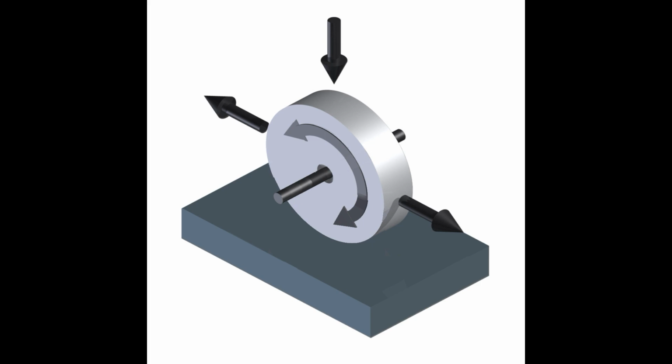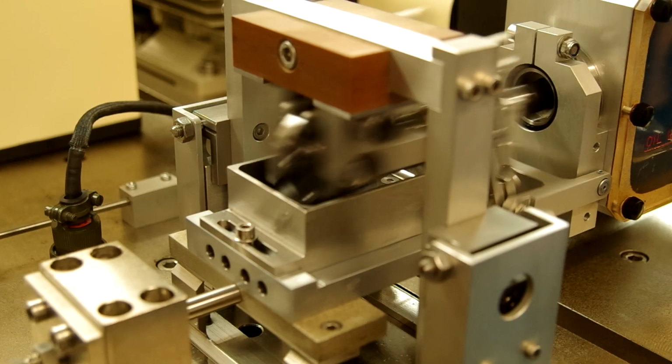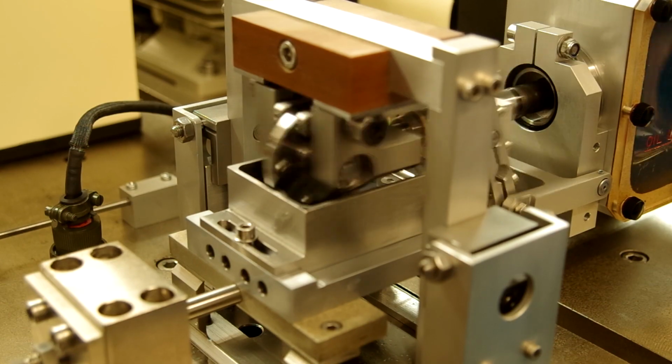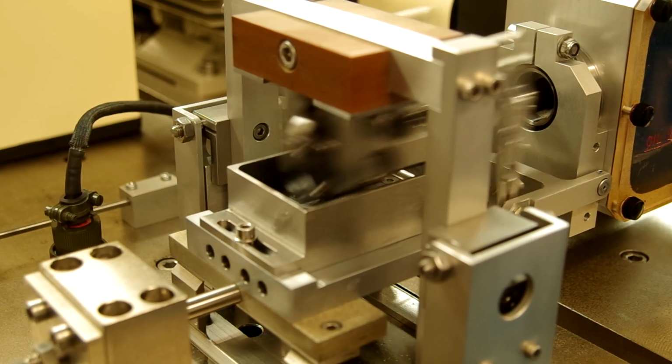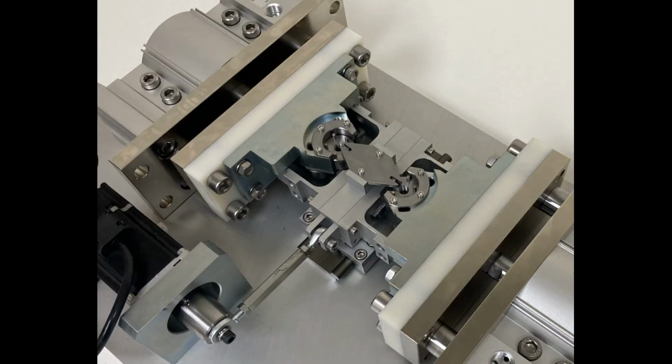The T55 is derived from various slide roll adapters available on our standard T77 reciprocating tribometer. In this design, a pair of 20mm diameter rod samples are loaded against plate samples which are mounted on either side of a reciprocating assembly. The maximum reciprocating stroke is 8mm and the minimum stroke is 2mm.